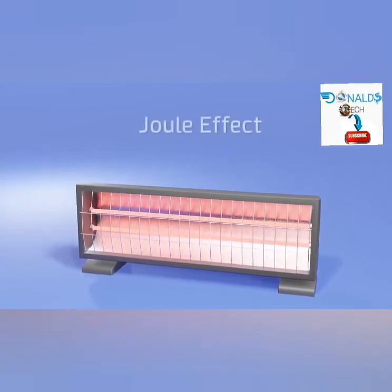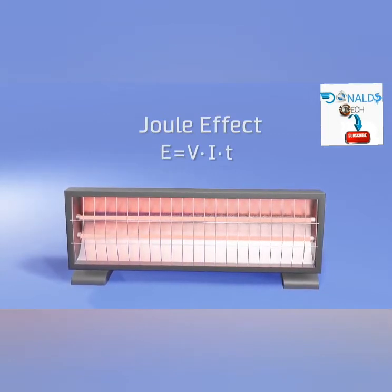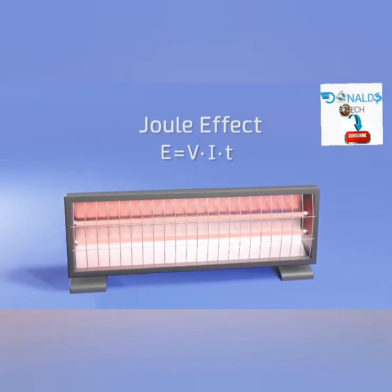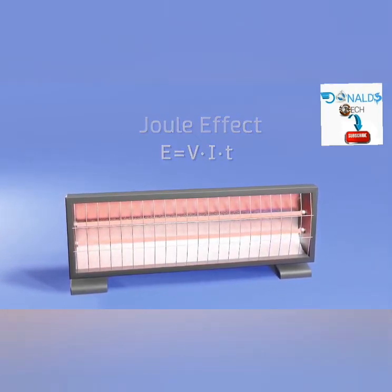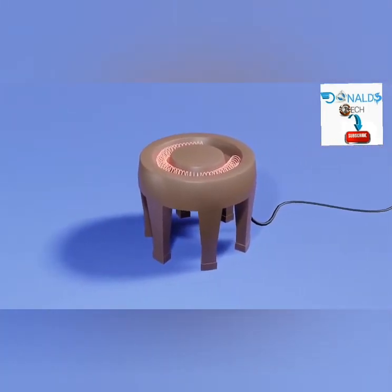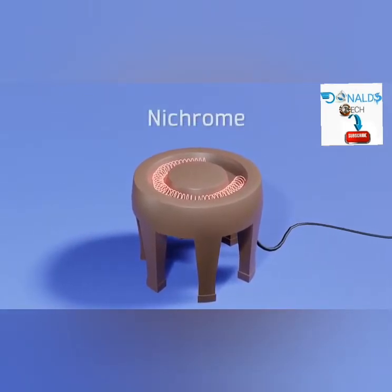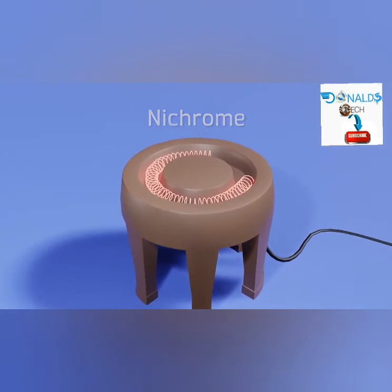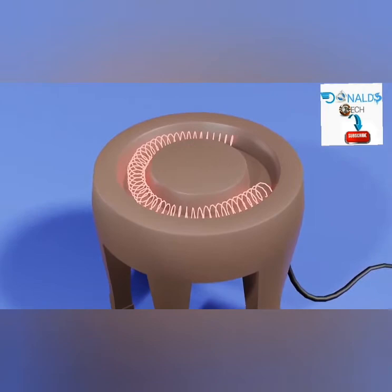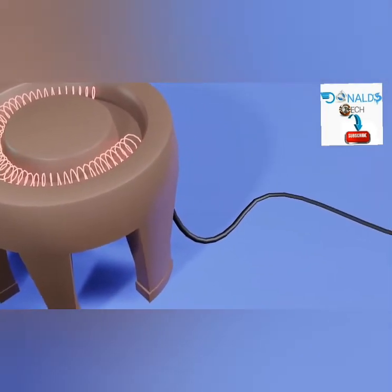the Joule effect. And we can calculate the energy dissipated in the form of heat as the multiplication between the voltage applied to the conductor, the intensity of the electrical current that is passing, and the time during which this occurs. The limitation of doing this is that the material could melt or oxidize extremely fast, leaving it unusable. That is why for such cases, alloys such as nichrome are usually used, which, in the first place, has a melting point of 1400 degrees Celsius, and also has a high coefficient of resistance. This last characteristic is precisely the reason why only that section is heated and not the cable that we plugged